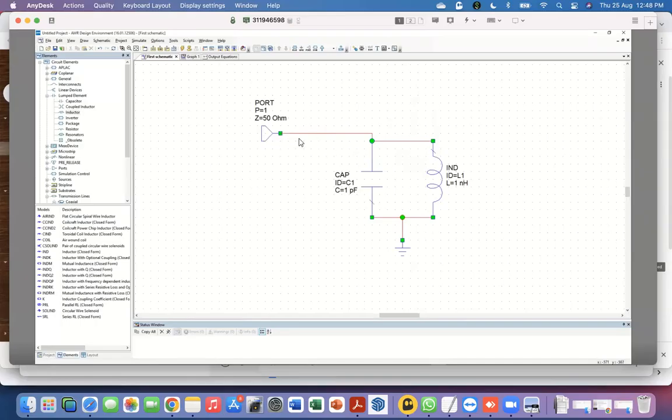So, in some simple sense, you're saying you have connected a multimeter, some kind of probe, at this particular point. And in this detector, even though I said it's both a source and the detector, this 50 ohm number implies that this point is connected to ground with a 50 ohm resistor. That's what this means. And a 50 ohm resistor, not a 50 ohm impedance, right?